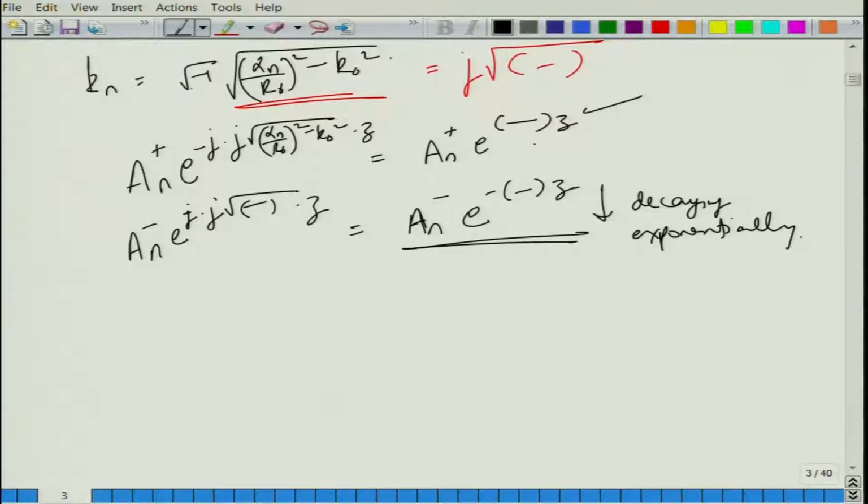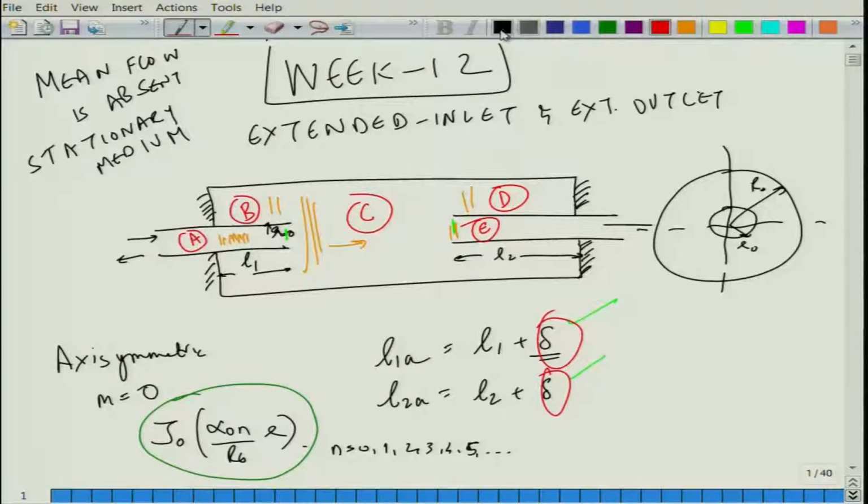So, a clever trick which is not quite given in books, but I am trying to present in a very simple manner, is that let us have a change of variable. When we set up the equations, wherever such a thing would occur, we will not at the inlet pipe, when you have z is equal to L, at z is equal to L the other section, because you see we are fixing the coordinate system z is equal to 0 here for this C part, and z is equal to, let me call this, z is equal to L3. Now, physical lengths L1 plus L2 plus L3 is equal to overall length L. This thing will not change even when you put this.